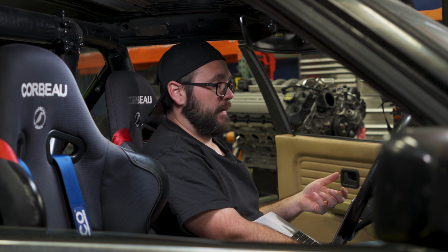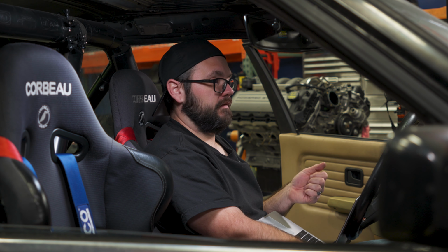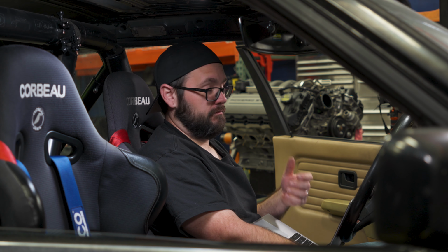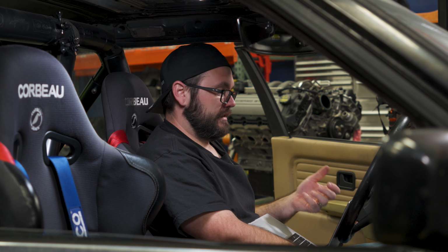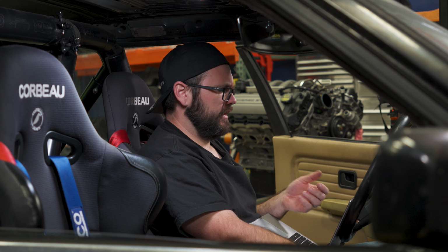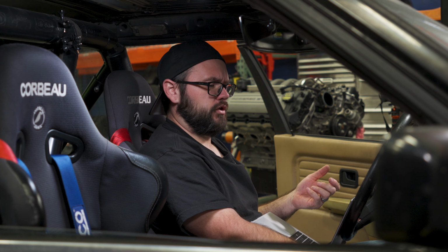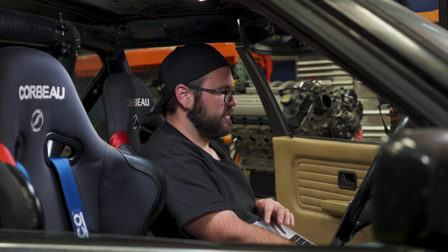The 52-pound injectors we did put in are a significant upgrade over the stock injectors. So this tune is currently set up for 19-pound injectors, so 52 is more than double the injector. Let's go over those settings, and then we're going to take a look at some of the other fuel and ignition tables, and I'll talk about what you should do if your vehicle is modified with, say, boost.